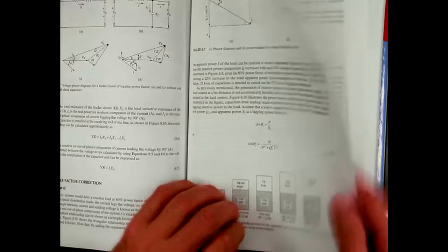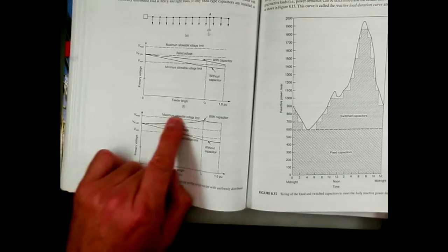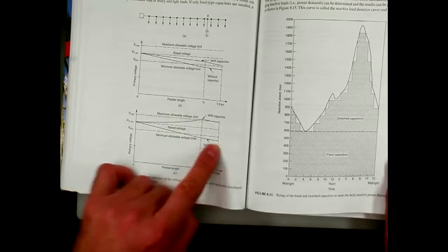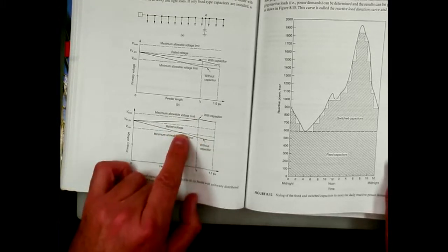You are going to operate at a very high voltage, right? Because just put Q equal to a leading power factor, and there is an equation here, right? Sorry, a graph that shows that the voltage is going to increase. Oh, here, right? The voltage is going to increase. Well, you have to keep it within the maximum and minimum value, right? In this case, for example, without capacitors, you got it there, right? So here you need to put either a voltage regulator or do something, right?